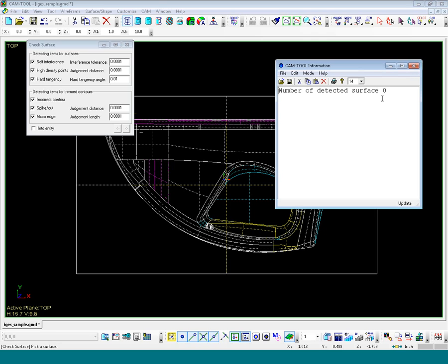But as we were told earlier, not everything that this detects is going to be an error. Some things just maybe slow down toolpath creation or things like that. Not necessarily something physically wrong with the geometry. If it says warning or error, then obviously you're going to have to do something to fix it. Usually getting your engineering department involved at that point would be a good idea.